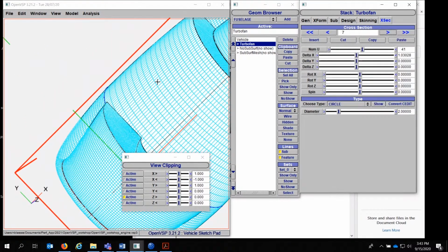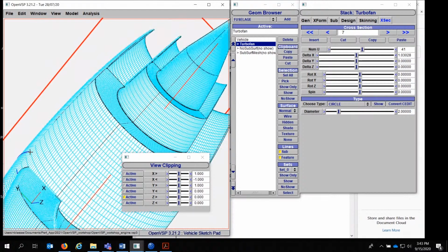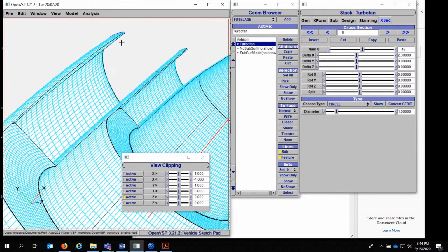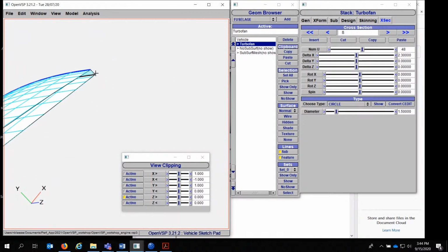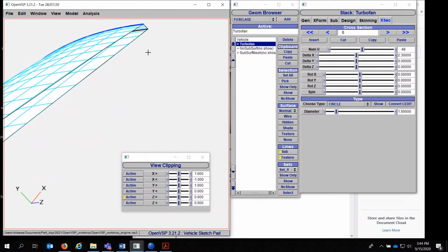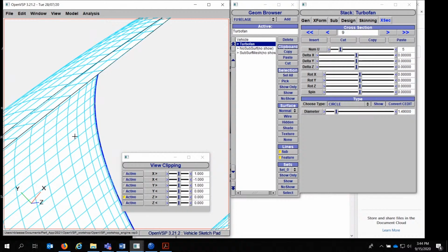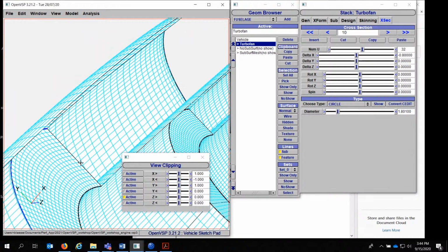Walking through, the next one is the max diameter cross section right here. You could move this forward or aft, make it bigger or smaller to change the nacelle shape, or if you had some kind of optimizer, you could probably run that through. Going to the back, here's my blunt trailing edge. It's just a very thin trailing edge on the back, and then it doubles back on itself right there. I put another subsection here so that I can separate this inner surface from the outer surface for the thrust drag bookkeeping issue. And then I moved it here.